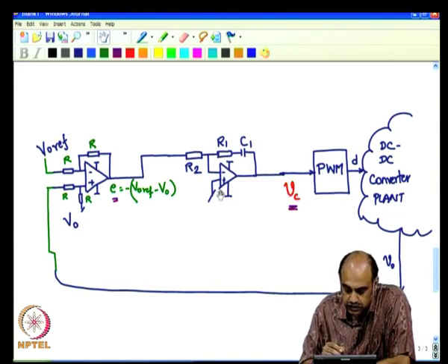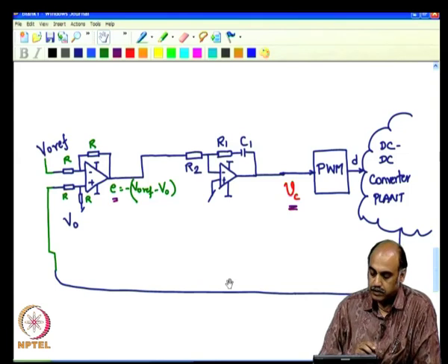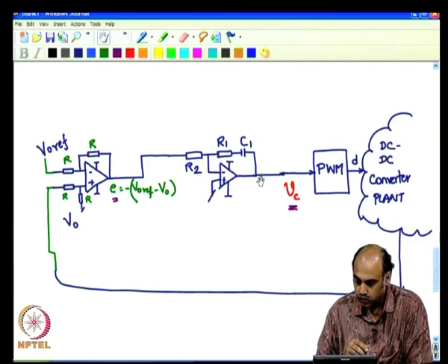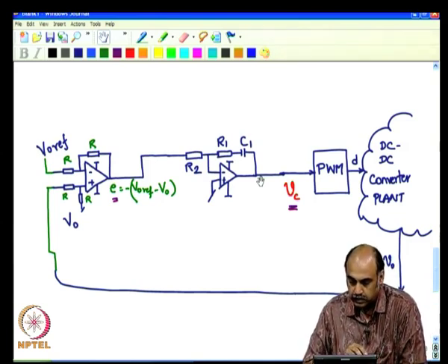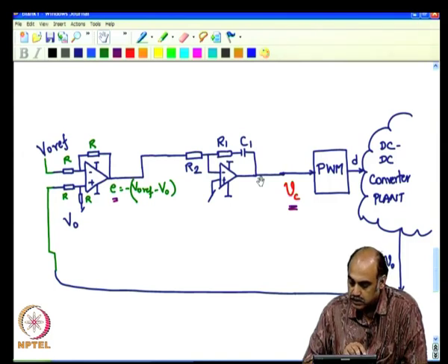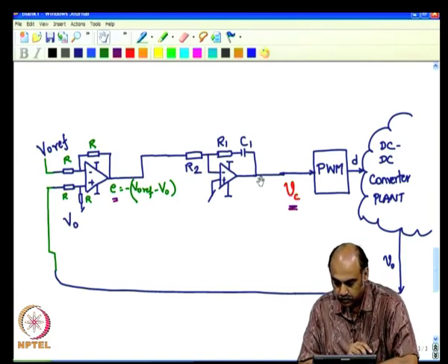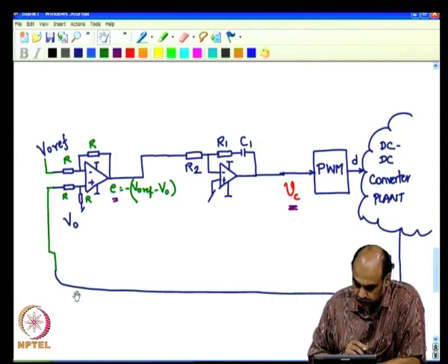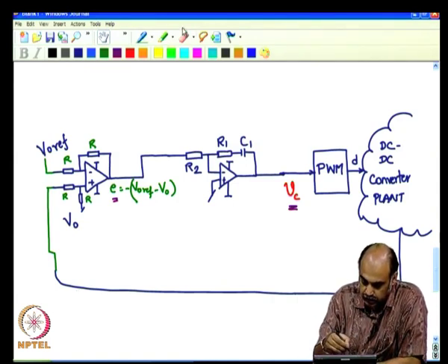Whenever you do changes in the circuit, keep track of the number of inversions, or like as we will later on do in a practical case, if you have lost count of the number of inversions, we shall, when we do the online tuning, first check whether the phase relationships are okay end to end, and then do the closing of the loop. Okay. We will get to that later, but right now try to keep an account on the number of inversions.